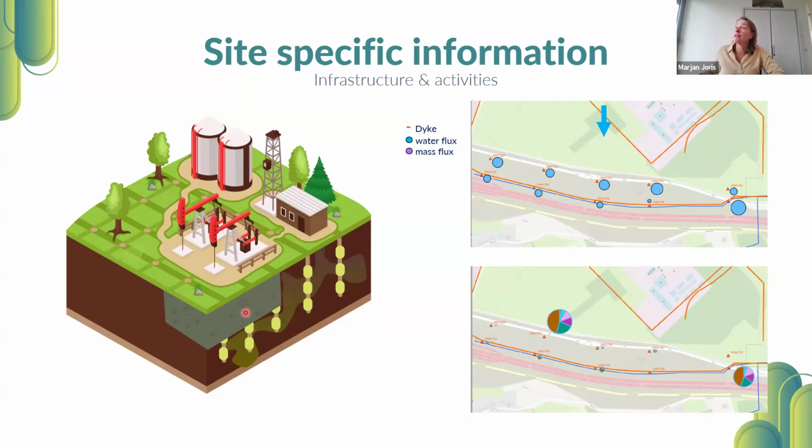What we can see over here is that if we would do concentration measurements just upstream from this concrete barrier, concentration could be high just because of accumulation of the contamination upstream from this barrier, although the spreading is not going through. The groundwater will find its way around or underneath, and contamination will follow the groundwater flow.